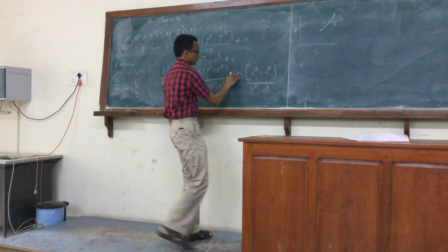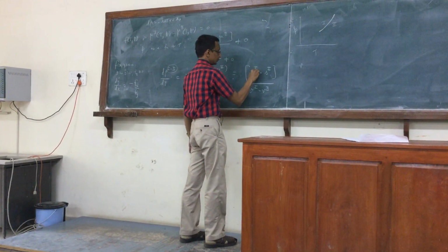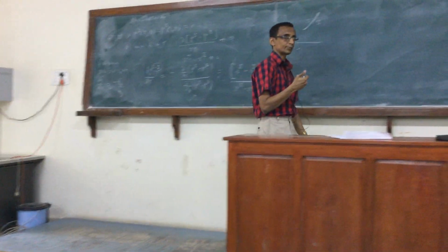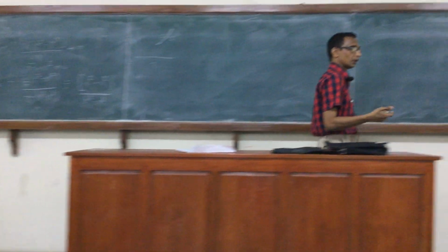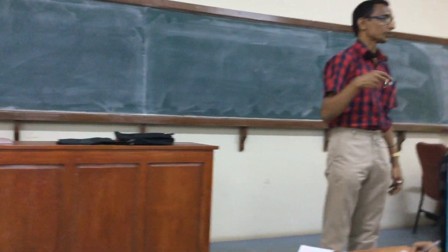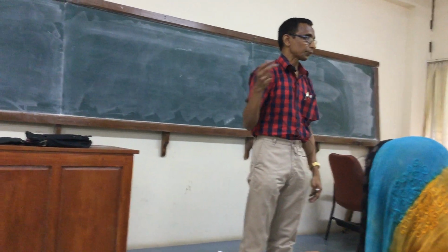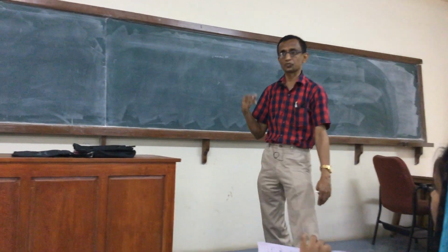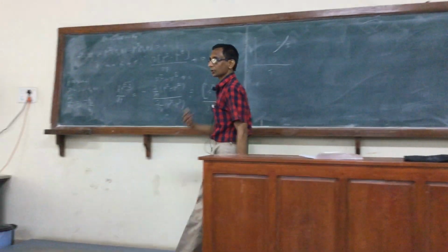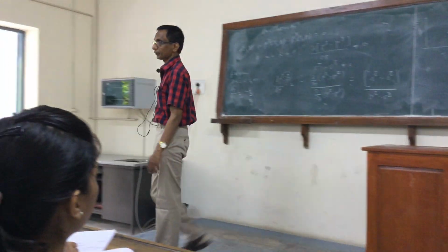So I can write this as, it's easier to remember, both are either I can write it as s2 minus s1 by v2 minus v1, or s1 minus s2 by v1 minus v2. So it's the difference in entropies of the two phases, the ratio of that with respect to the difference in specific volume. That is what the slope of the coexistence curve is.